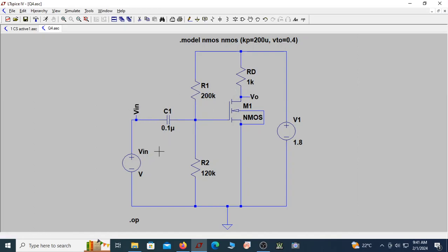Before we actually see the response of the circuit, I have to see whether all DC conditions match my design or not. When you rig up the circuit diagram, you have already designed the value of drain current that should flow, and what VDS and VGS are, all those things, which I can see.